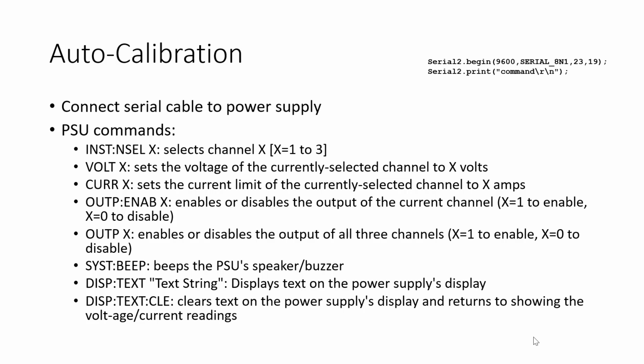Can you set the voltage when it's on, or do you have to turn it off to change the voltage? You can set it. When I have my code stepping through them all, I don't have it turn off in between because that would take a lot of time. I just leave it on and step it through. You can change it while it's on, even from the front buttons. Okay. Any questions about that? One other thing I should note as well, there's a chance that people who have used these power supplies in the past have set the voltages to crazy values.